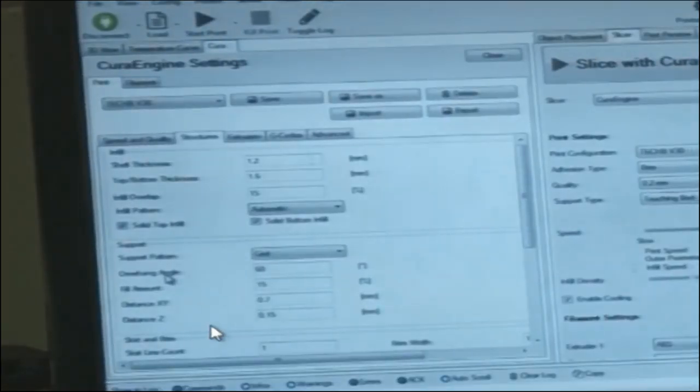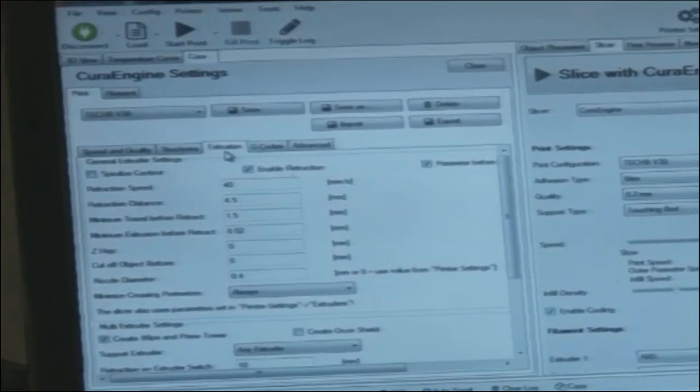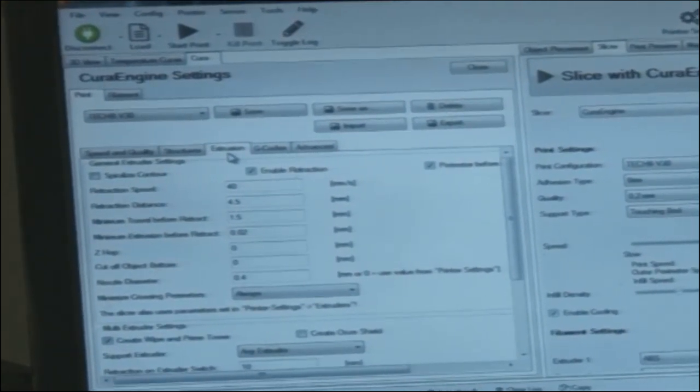So the overhang angle is 60 degrees, and next, we need to see whether there is anything overhanging in the CAD model. If there is an overhang in the CAD model, then we need to put in this angle. If anything is overhung, then we need to provide this support, and only then can we proceed further. So the overhang angle has to be decided.